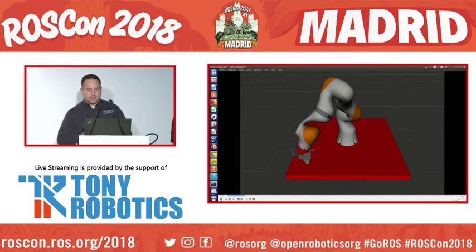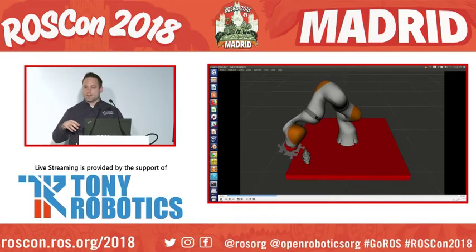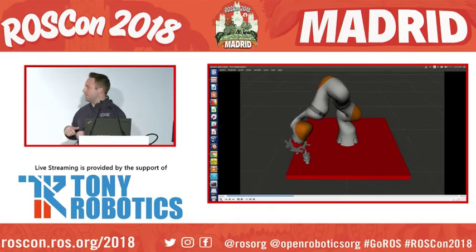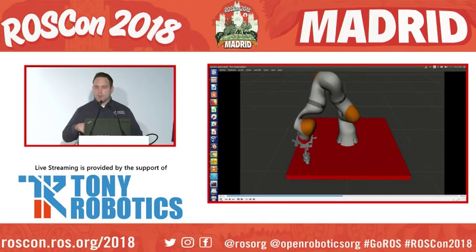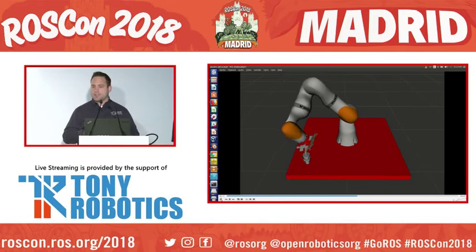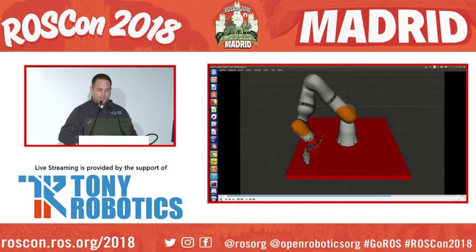So here's a complex puzzle piece that we're doing. I think it has about 400 Cartesian points with the z degree of freedom free. We leverage TrajOpt to manipulate that extra degree of freedom to come up with this complex Cartesian path. And it's about 8 degrees of freedom, so 7 degrees in the robot and the tool z degree free.